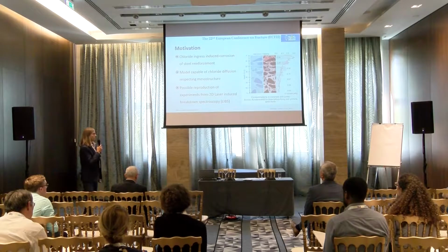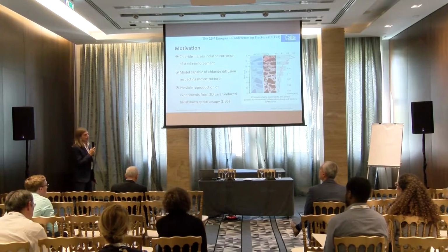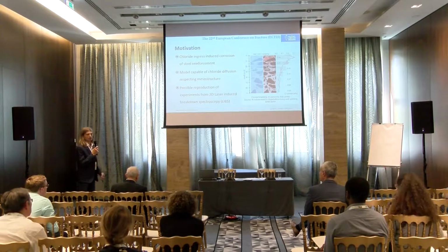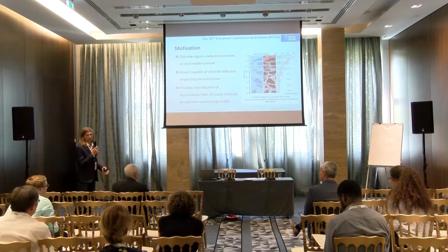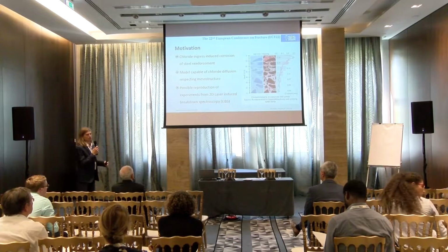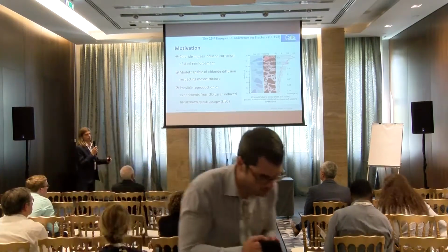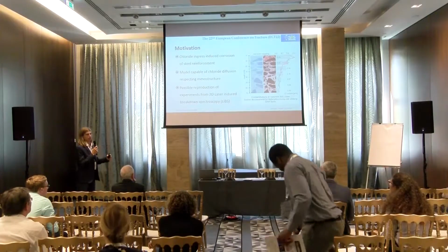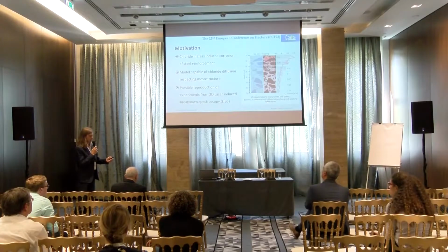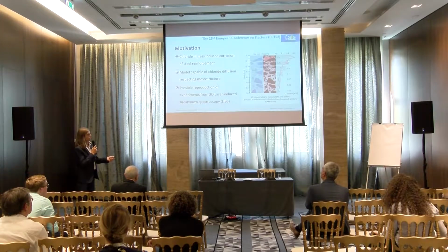The motivation behind the work is modeling and the analysis of the chloride ingress into the concrete. And this has an impact on the durability of the concrete because of the corrosion induced by the chlorides from de-icing agents penetrating to the level of the reinforcement.